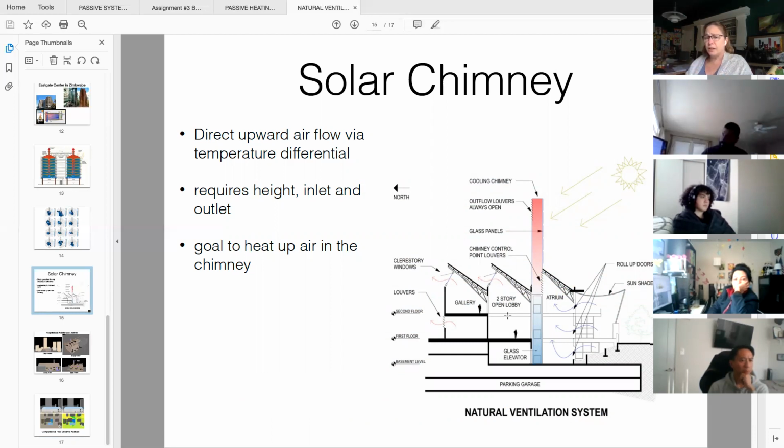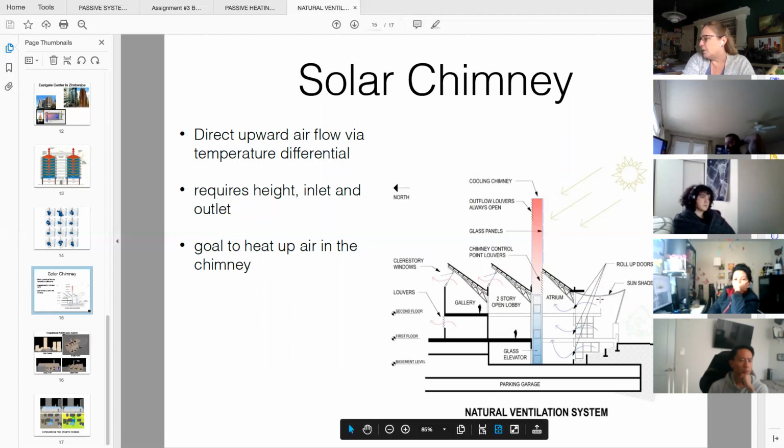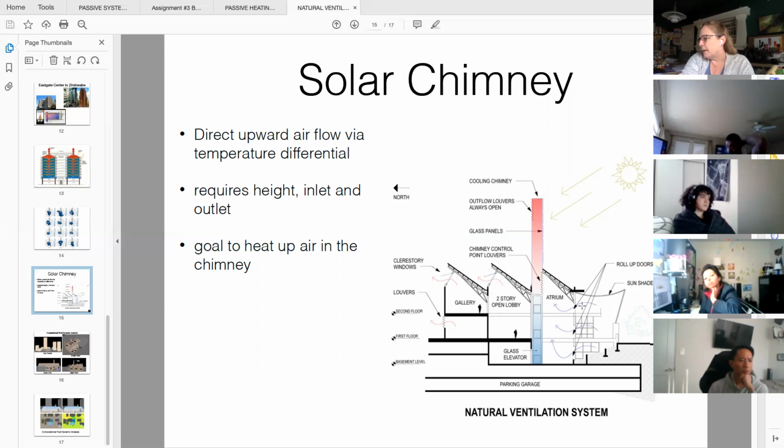We're also passively trying to heat the building in the winter. So natural ventilation cooling in the summer, passive heating in the winter. All the floors are concrete with large things on the south side. And this image doesn't show it, but we were using deciduous trees on the south side. In the summer, the trees would block the direct gain coming into the space.